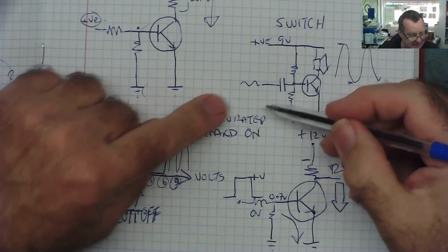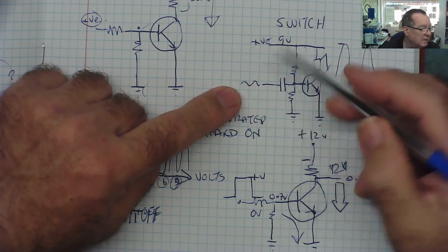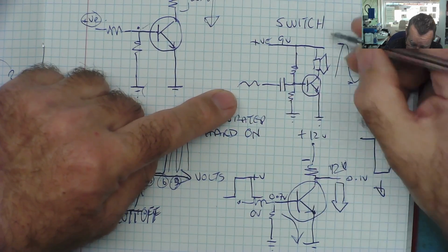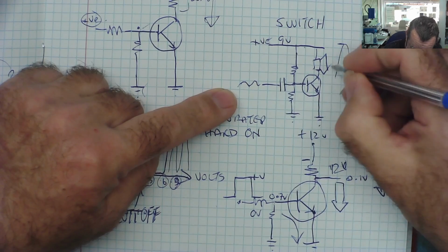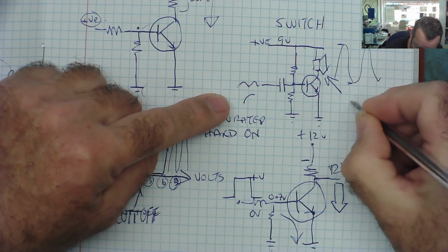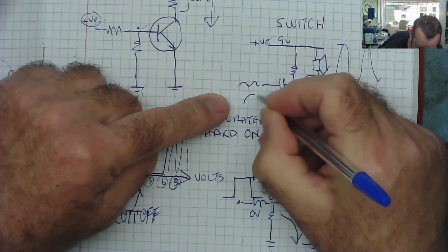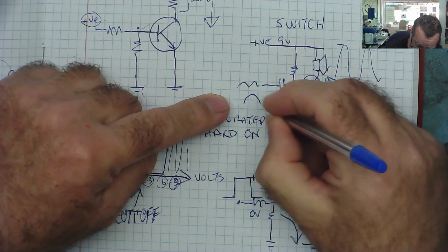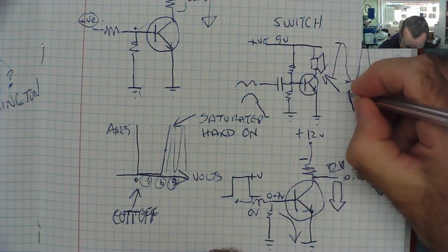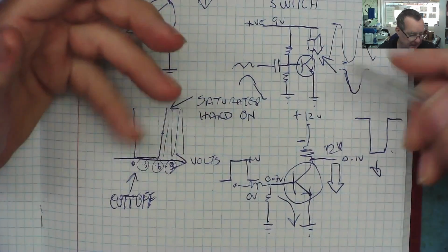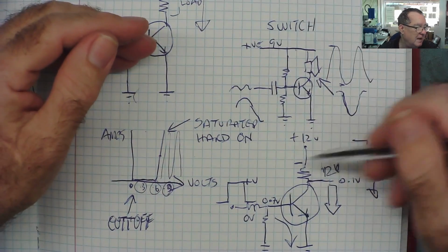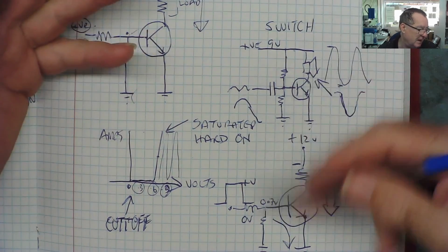And the same applies with this amplifier. I'm sure you can see that now. So as this signal goes more positive, the transistor turns more on. In actual fact, what you see is that the waveform, this is getting more positive on the collector here. This is getting more negative. Okay, it's upside down. It's inverted. And as this goes through 0 to more negative, this goes to more positive, and so on. So a transistor is a switch, is an amplifier, and it also inverts the signal.